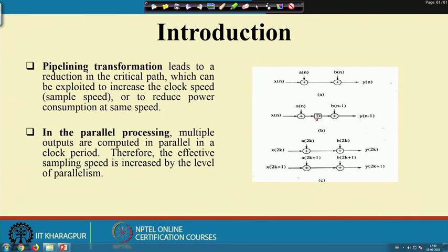But here, as I have put the delay in between, in 1 clock I get the output over here, I have to wait for 1 clock, and after that in the next clock I will get the y1. So once I got the y0, after that I immediately get the outputs in a flow. It is something like why this term pipelining comes, it is just like if you want to pass water through a pipe.